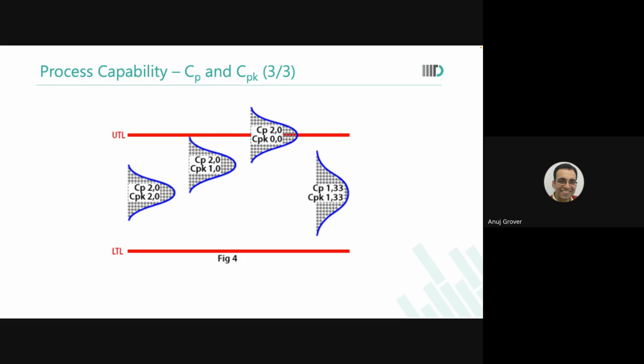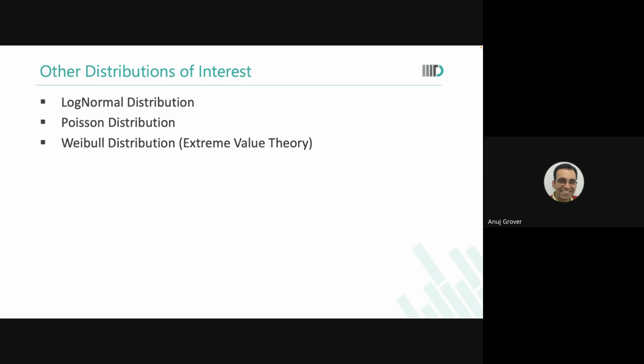So yeah, this is another view of that. Now, what is important to realize is that all the CP and CPK business that we just talked about is valid if you have a Gaussian distribution. But think about leakage. What is the formula of subthreshold leakage? Something into e raised to the power of (V minus VT) and something. We're talking about something exponential there. Do you think a Gaussian distribution will be valid?